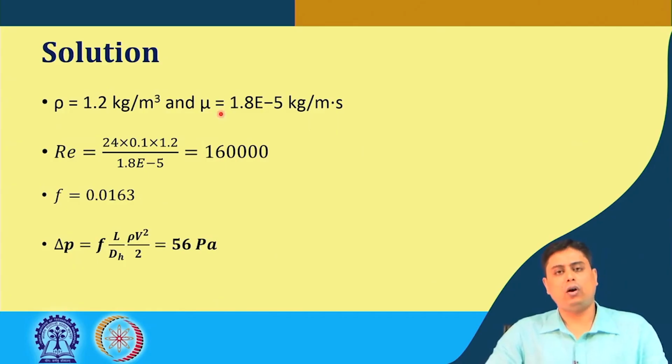So, now in order to find out the overall pressure drop, which is directly linked with the flow parameter, the Reynolds number, or how the flow pattern basically is, is it laminar or is it turbulent, because based on that you can use a particular drag coefficient or the friction factor. So for that, at first we have to calculate the Reynolds number of the flow for the scenario when there is no flat plate inserted.